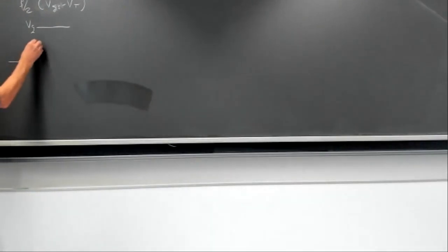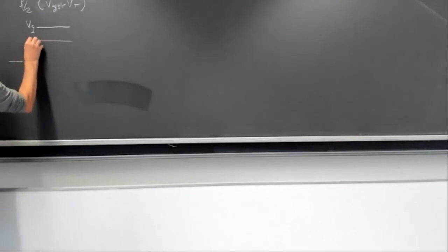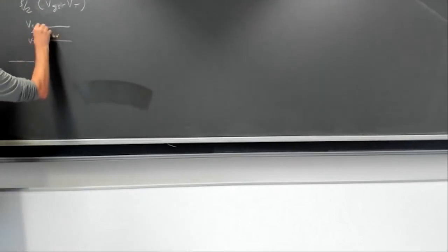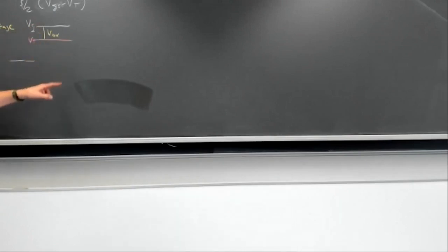Okay, and now there's a certain threshold voltage. Let me draw that in another color. That's VT. And where's the overdrive in this picture? It's VG minus VT, right? So this is the overdrive. Is it clear? This is a picture of voltage. I was just talking about the source and the gate. And the gate, by definition, because you're running above threshold, is above the threshold voltage by this amount, the overdrive. Now the drain is at some other voltage.